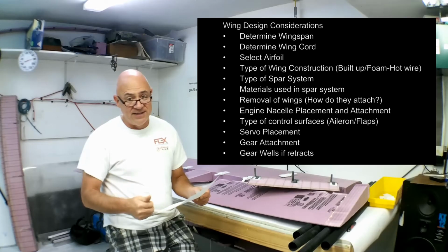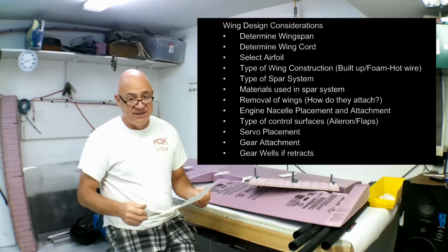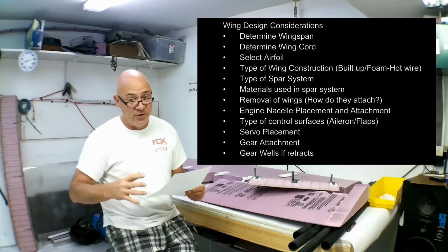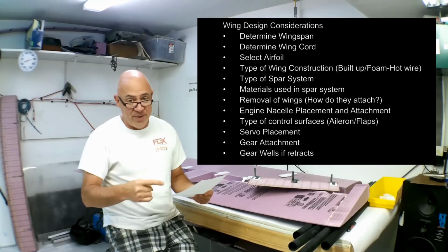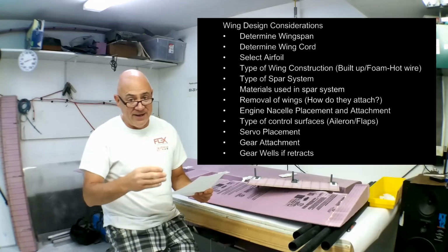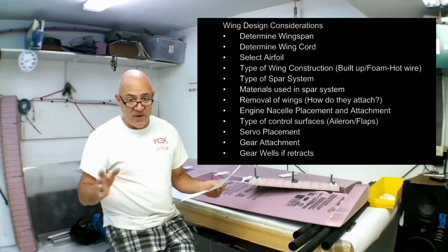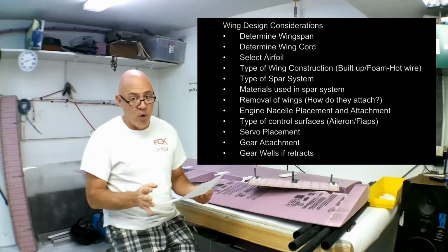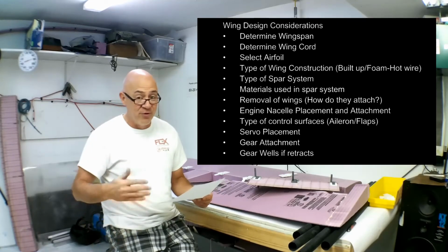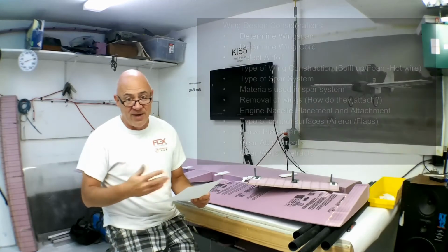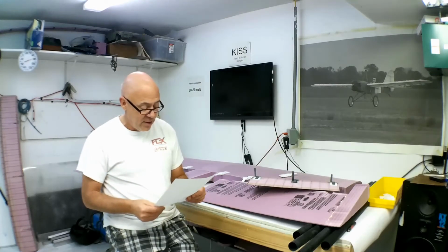There's a couple of designs out there, and I'm not going to throw anybody under the bus that designs B-29s. And these are people that you can buy their plans where they cut the spar in half and expect you to build a little box that wraps around the landing gear. Dumb design. If they would have moved that spar 2.5 inches forward and had another secondary spar about 4 inches behind it, it would have been like a real B-29, and you wouldn't have had to cut the main spar to get the wheel to go up and down.